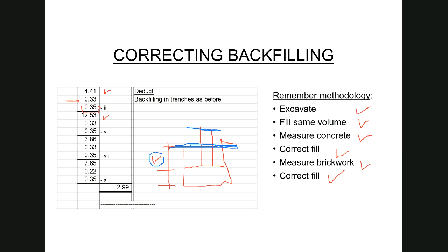Okay, and then for detail 2, it was the 12.53. It is still a 1.5 brick wall times 0.35. Then detail 3, also a 1.5 brick wall. And then the last detail 4 was a 1 brick wall, and there I have the 0.22, but I'm still using the 0.35. Okay, and then just a reminder that all these dimensions over here are negative, and I am getting that right by putting the deduction above the description, which is indicative that all the dimensions on the side are negative.